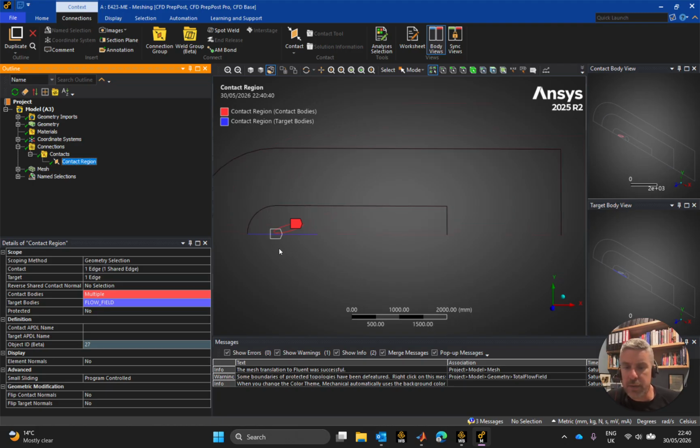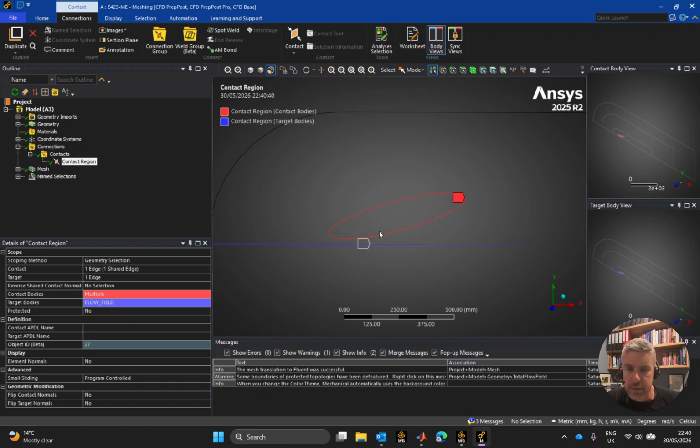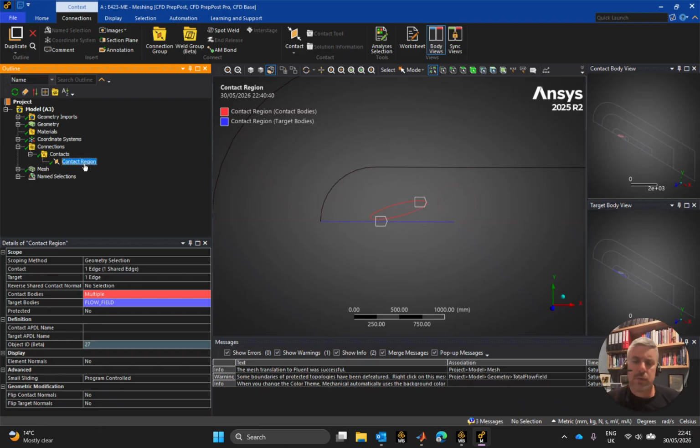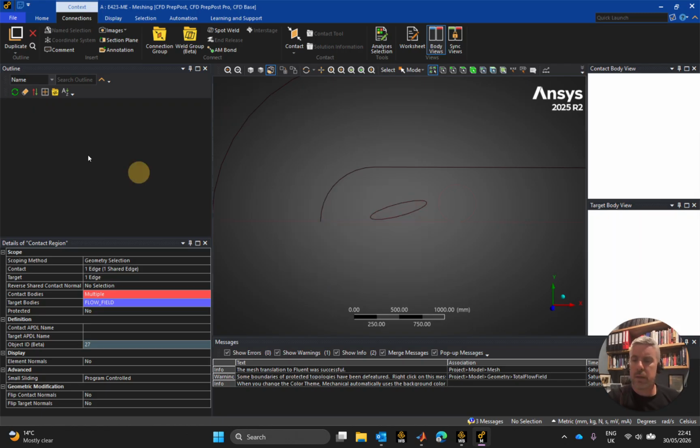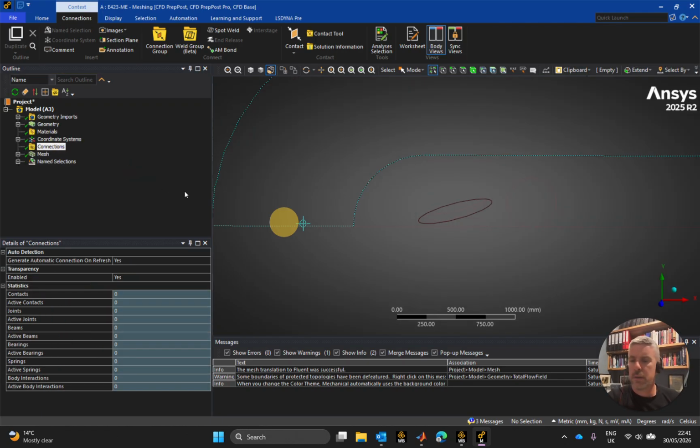And what I can see here on this one now that I am looking at it is that it is noticing that I have some sort of a contact region between my buffer region and the track, where I don't really have a contact region there. This section here should be a track. It's probably going to come up as an interface, more so if it's a contact region, it'll come up as an interface, which is not an interface. So what I'm going to do is delete that out. Just delete that away. I shouldn't have to regenerate the mesh from this.